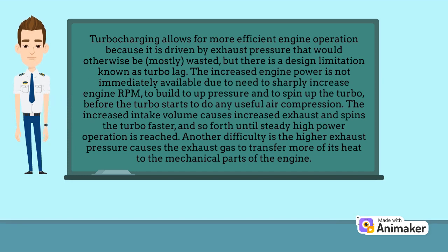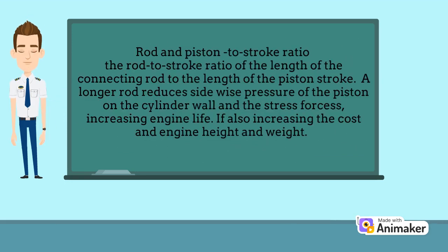Increased exhaust spins the turbo faster, and so forth, until steady high power operation is reached. Another difficulty is the higher exhaust pressure causes the exhaust gas to transfer more of its heat to the mechanical parts of the engine. Rod and piston to stroke ratio.